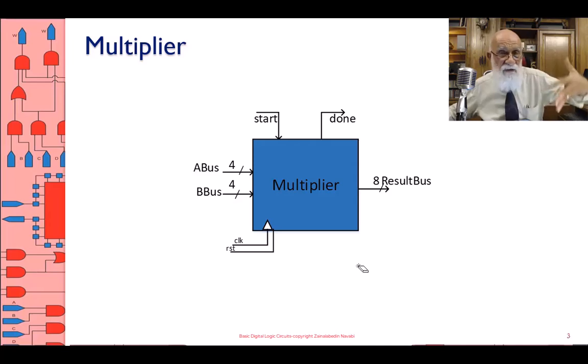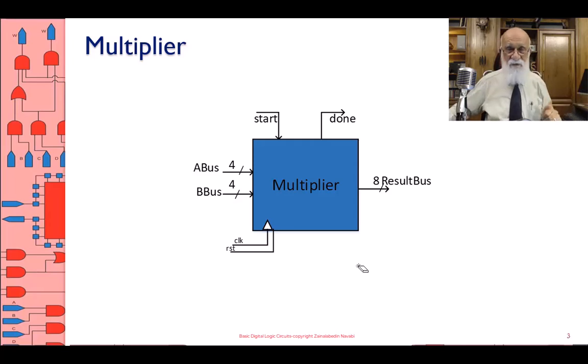As our first RTL example, a divider by subtracting B from A when you are dividing A by B, subtracting B from A until you can no longer subtract. That's a perfect algorithm. It's not good. It takes a lot of clock cycles, but it gives you the sense of RTL design.